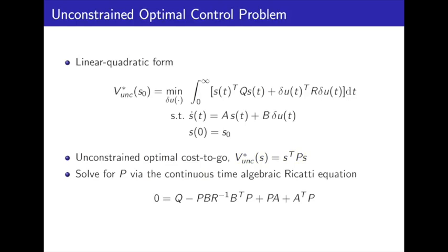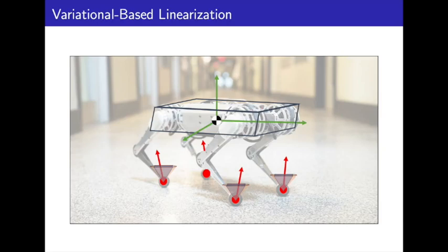Two complications of quadruped balancing pose obstacles to direct implementation of this control strategy. First, this optimal control problem requires linearized dynamics, and second, the optimal control problem does not allow for constraints on the variation to the control input. Even using a simplified model of the robot, its dynamics can still contain elements of the special orthogonal group SO3. Traditional linearization techniques do not translate to this type of nonlinear manifold. To account for this shortcoming, we implement a linearization technique referred to as variational-based linearization.